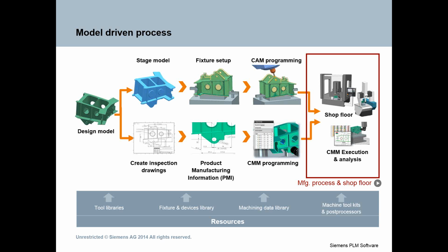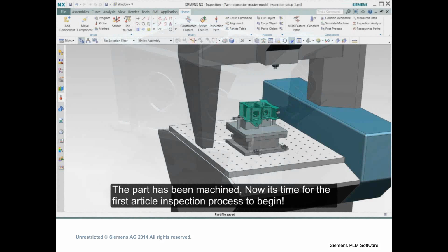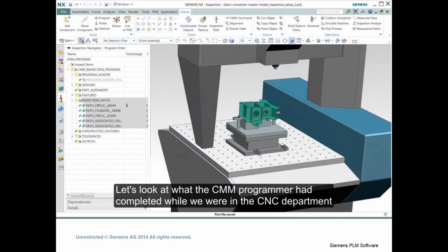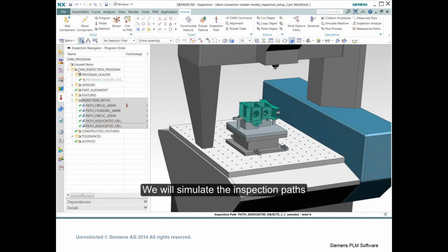Here we'll use NX to simulate what will occur on the shop floor in this demonstration. The part has been machined. Now it's time for the first article inspection process to begin. Let's look at what the CMM programmer had completed while we were in the CNC department. You can see the inspection paths now have been selected and are completed. Any modifications made, we'll now go back and simulate what is happening on the shop floor inside of NX CMM.